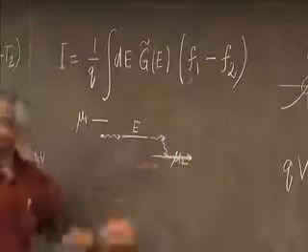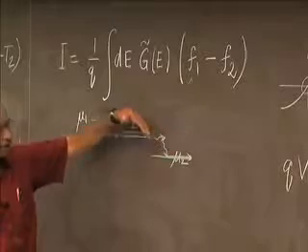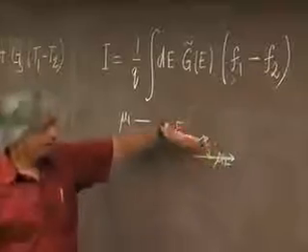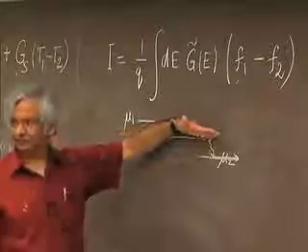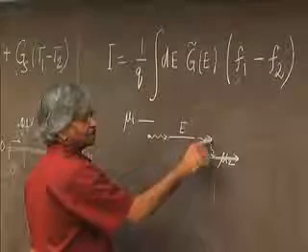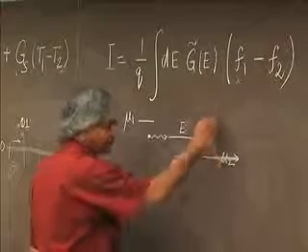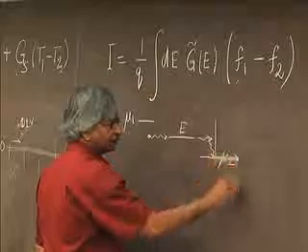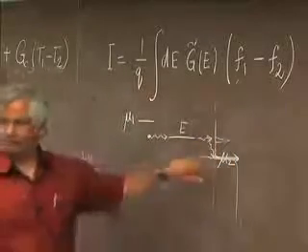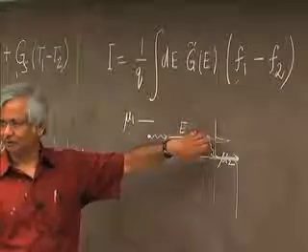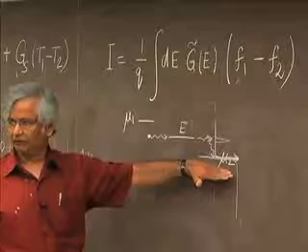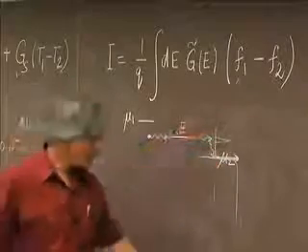According to this ∂f/∂E function, once it has come back to equilibrium the way it wants to, it won't have all these hot electrons up here, because when you look at the occupation, once the electron comes out here, this contact really likes to have a Fermi function. And an electron up here looks like an anomaly. It looks like a big spike at an energy that shouldn't be there. And so all inelastic processes will quickly lower it down. That's what it does.